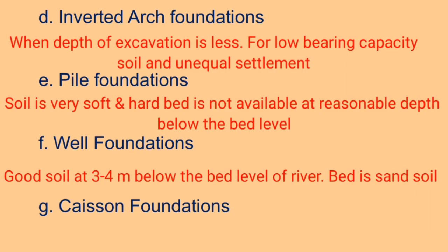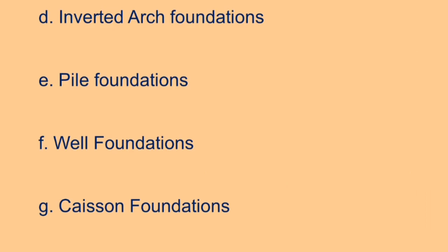Now, caisson foundations. This type of bridge foundation is suitable when a hard strata bed is available near to the river bed but the depth of water is excessive and it is not economically possible to exclude water to form a dry bed for sinking the wells to provide well foundations.